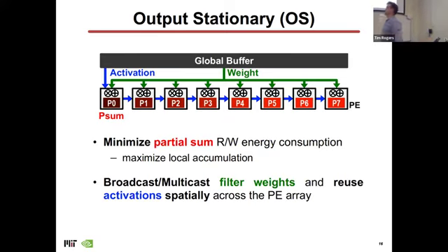We started last lecture to go over what output stationary looks like, abbreviated OS, where essentially we're keeping the partial products local to each processing element. We're flowing the activations out along the NOC, the network that connects the PEs. So these activations aren't changing as they go from one processing element to the next. It's just taking them and streaming them through. And once you fill the pipeline, the thing is active the whole time. And then the partial products are getting accumulated within each one.